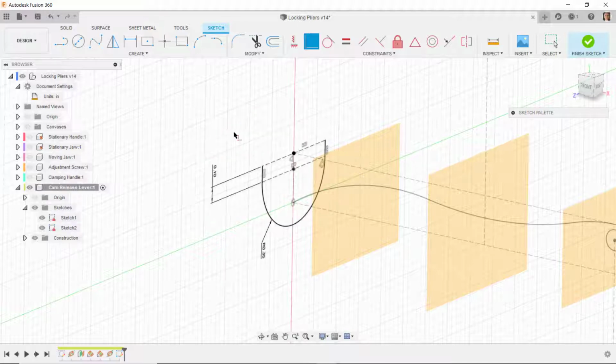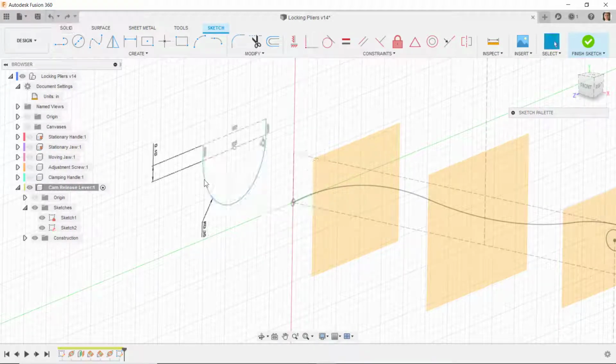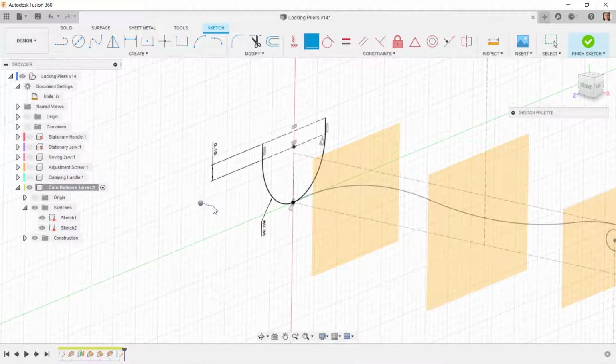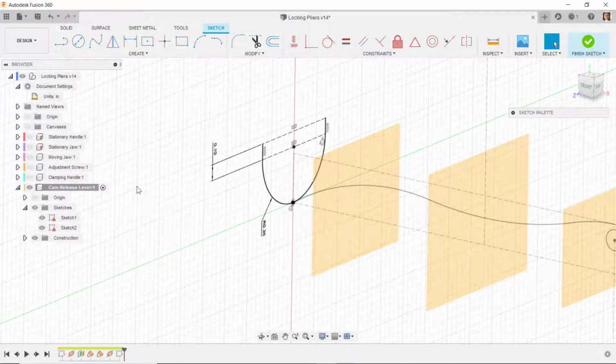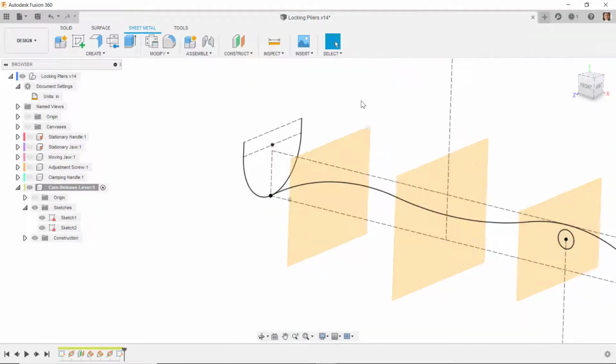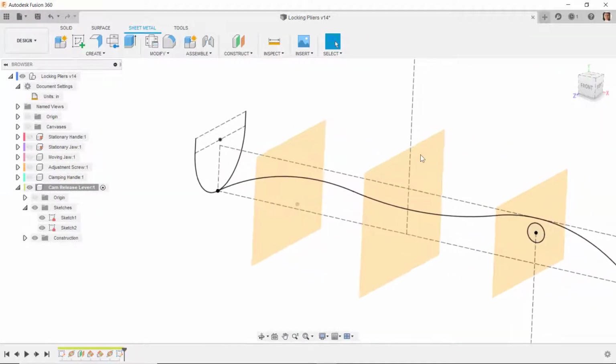of this line, so I have those coincident, and everything turned black, and I realized that I really want this point up here. I don't really care where that point is, so let me undo that, and I'll do coincident again, and I'll shift, get the midpoint of this curve, and I'll put that at that location. So that sketch turns dark, that sketch is fully defined. We're ready to do our next sketch.